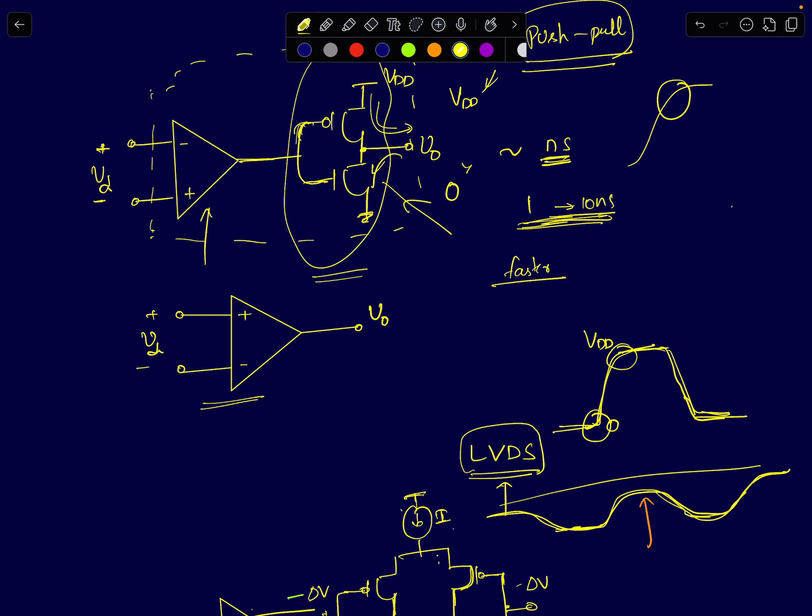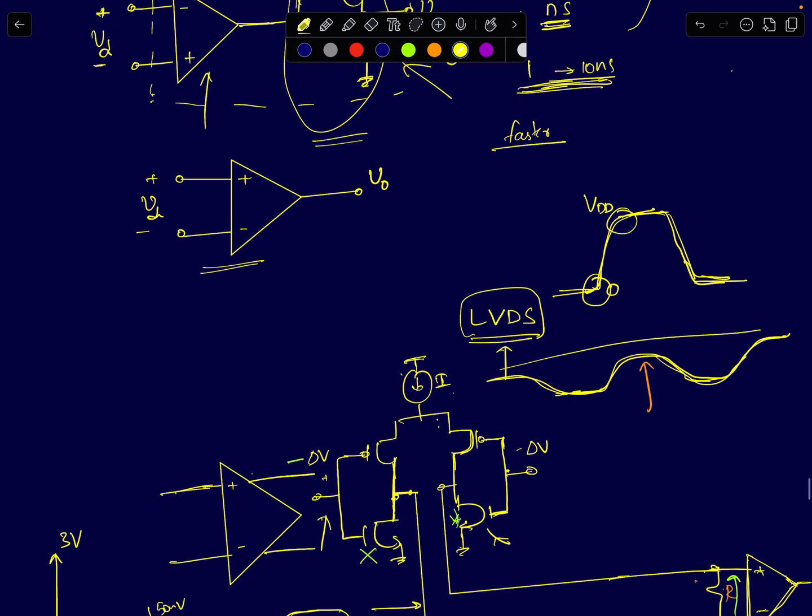Now, since we are talking about speeds, take any digital logic gate, if you analyze a simple CMOS inverter based circuit, when the output of a CMOS inverter goes from, let's say, logic 0 to logic 1, the CMOS inverter's gain is usually maximum at the mid point, the high gain point. So let's say initially the output is logic 0, and I've applied a logic high, and then the output will now start charging to VDD.